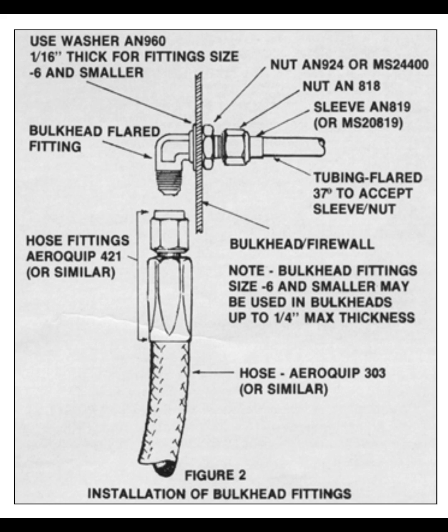How much slack must be left in a flexible hose during installation? 5 to 8% of the total hose length. How often should flexible hoses be clamped in place? Every 24 inches.